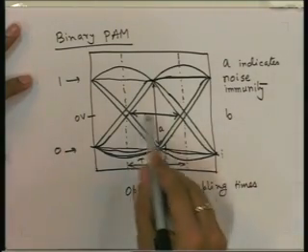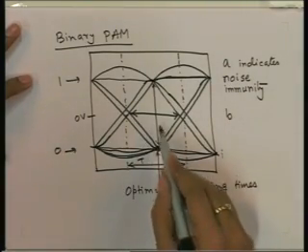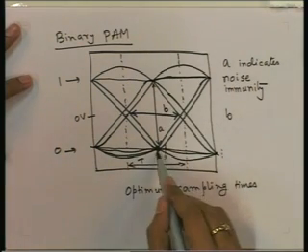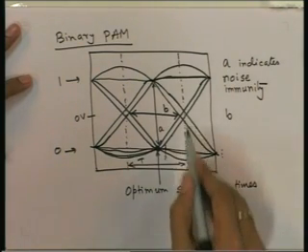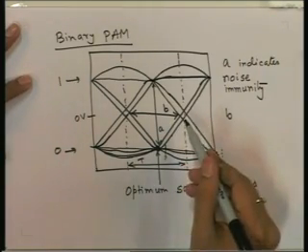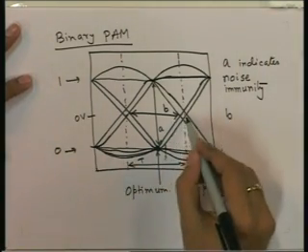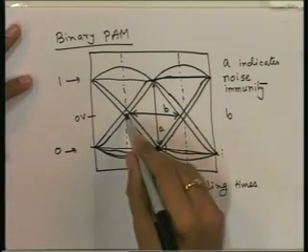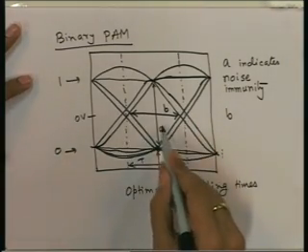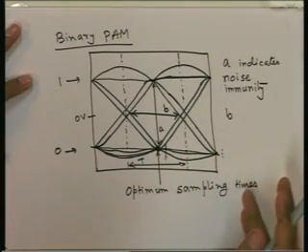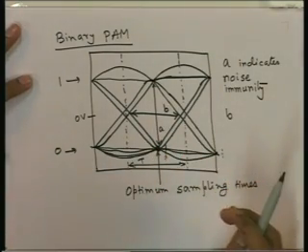That depends on this B, because as you can see, if the error is B by 2, here it comes here, then sampling here you will not be able to judge at all anything about the bits, because they will be near 0 volt all the time, here, here. So, more this gap, the better for sampling time error immunity.